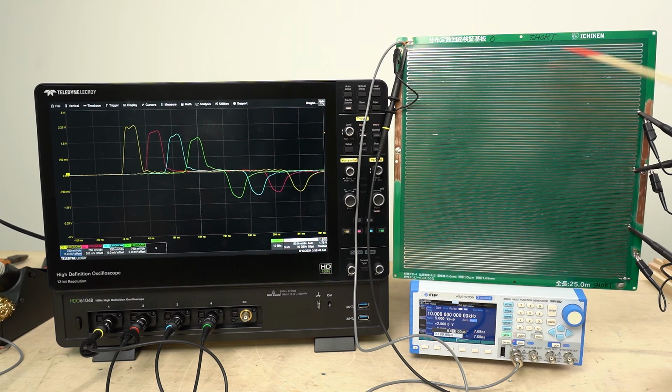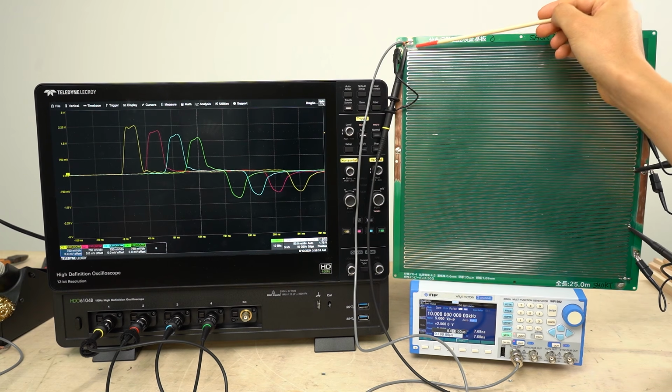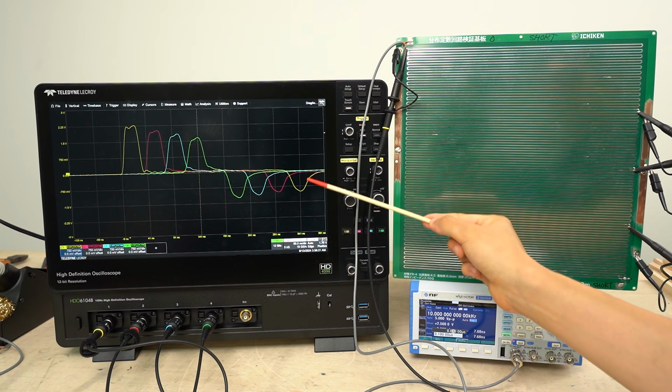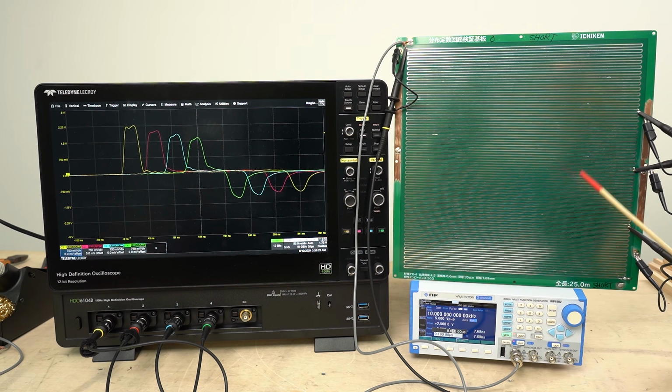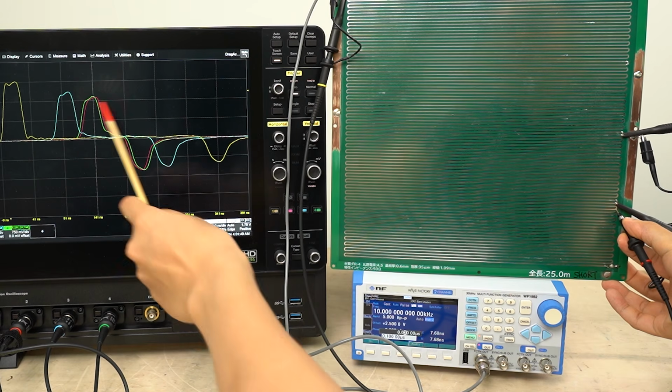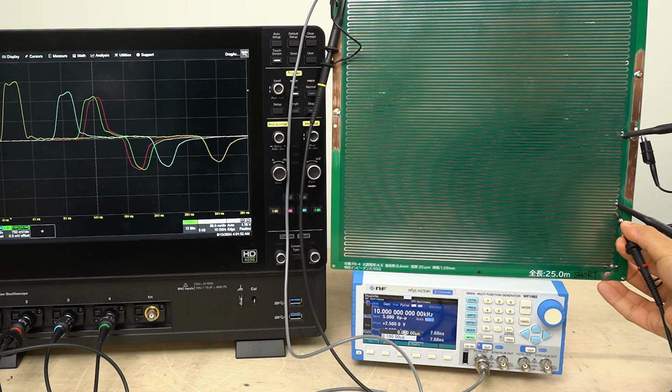At the 25% point, this is what you get. And back at the starting point, where the pulse was applied, this is the waveform. At the short-circuited end, the voltage reflects back as a negative wave. Now, let's take a closer look at the voltage near the short-circuited end. Keep an eye on the red waveform. The voltage moves forward.